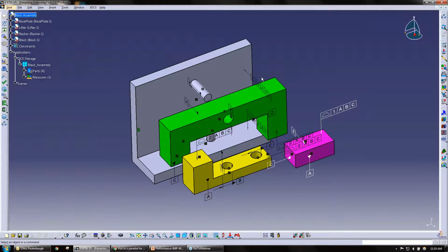So if you get parts that have GD&T already on them, the steps to embed and pull that GD&T into the software are as follows. We have the update model button. If I click on the little drop down here, we have a few different update buttons and deletes. The third button over here, we have an update GD&T. I'm going to go ahead and click on that.